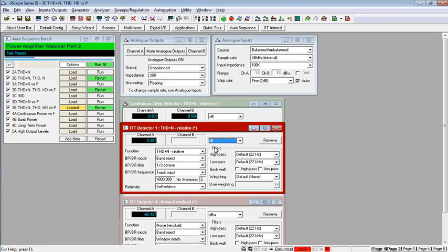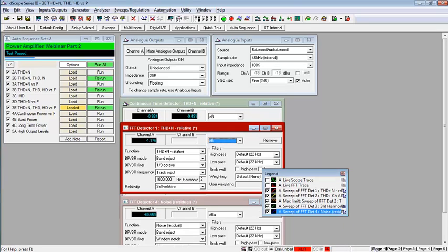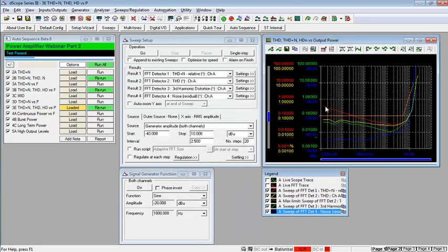Well, the fact that it's self-relative is telling us that we're calculating the distortion and noise energy as a ratio of the signal amplitude. So we're comparing the amplitude of the signal with the residual noise and distortion. And when we look at the low amplitude end of this sweep here, what's happening is that the distortion in relative terms is reasonably flat.